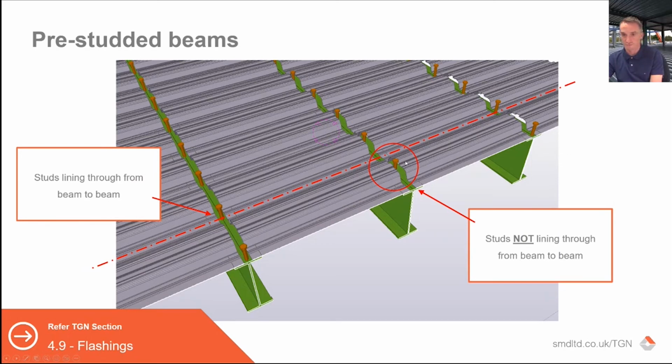So naturally, whilst you've designed that based on the code stud resistances, that doesn't have the concrete cone around it that will necessarily mobilize the stud resistance intended by the code. So it's important to integrate the two. We will always do that on jobs that we do. We send a drawing out that has stud setting out, or at least deck setting out, so the fabricator will know where to start the studs. The other thing that I mentioned slightly earlier, or in answer to a question, is to use crushed ends in a scenario like this.